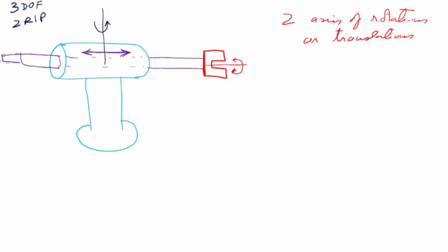Okay, in this case, where is the first one? Let me put my z axis like this. So z0 and z1 come there. Axis of rotations. Next is the axis of translation. It is translating about this axis, like that. So that's my second axis, z2. That is the translating axis. z3 is the rotation axis here again. That's my z3. So that was simple. The z-axis is the axis of rotations or translations. In this case, there are 2 rotations and 1 translation.